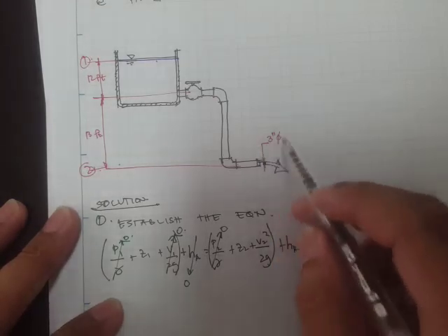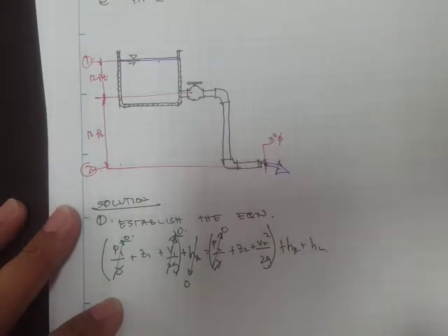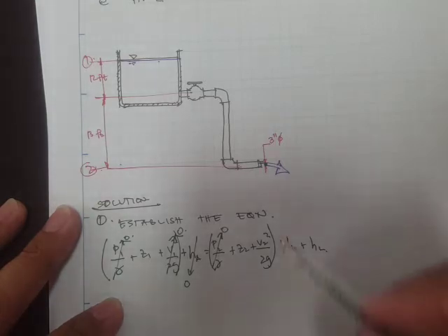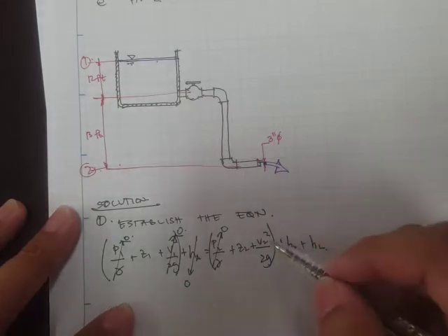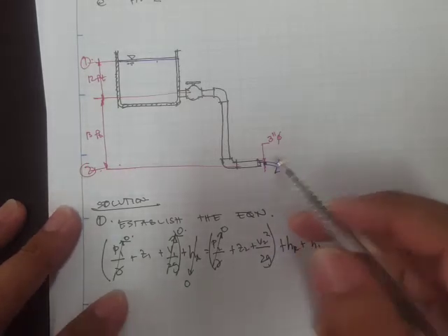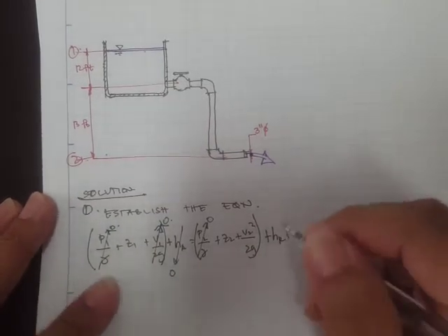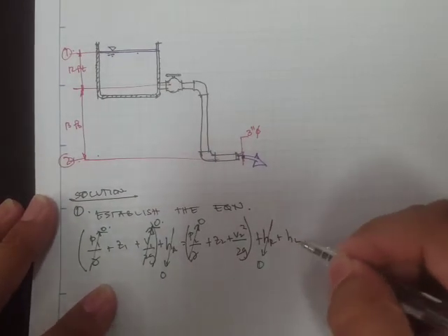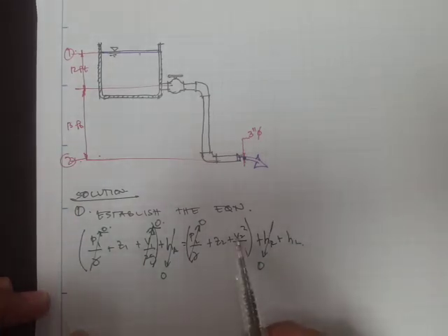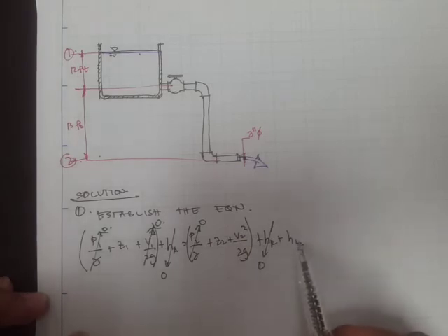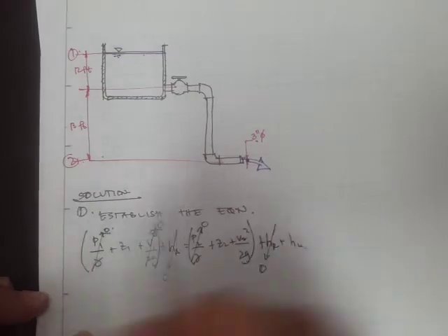by this dimension, it says here 3-inch diameter, then if we apply the continuity equation, the flow rate equation, Q is equal to AV, then we can solve for this V sub 2 squared. And for our H sub R, we don't have this, and this one is present, and therefore the only unknowns are the velocity and this H sub L. But the velocity, you can solve using the flow rate equation.